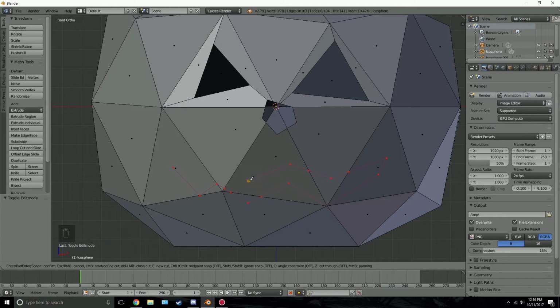And what I'm doing here is I'm kind of aligning wherever I click to down here. So you can see these two are aligned. This one is kind of aligned with this one, and this one's a little bit in line with that one. So it's something similar to that, and then I'll click right there. Once you're done, press enter, and that will create the face.